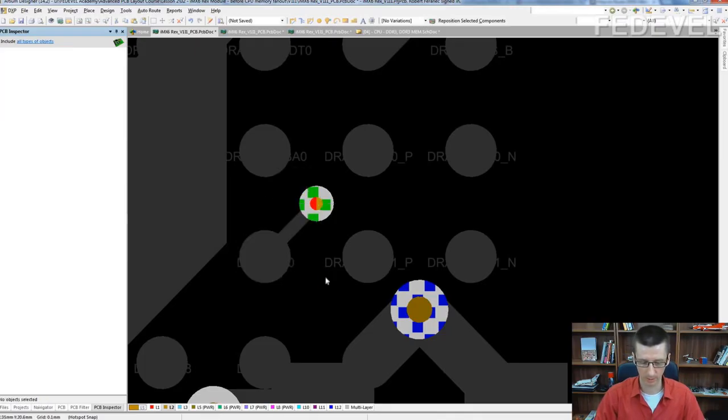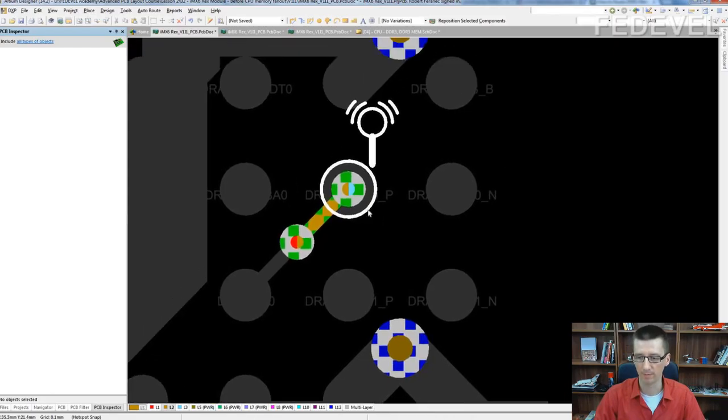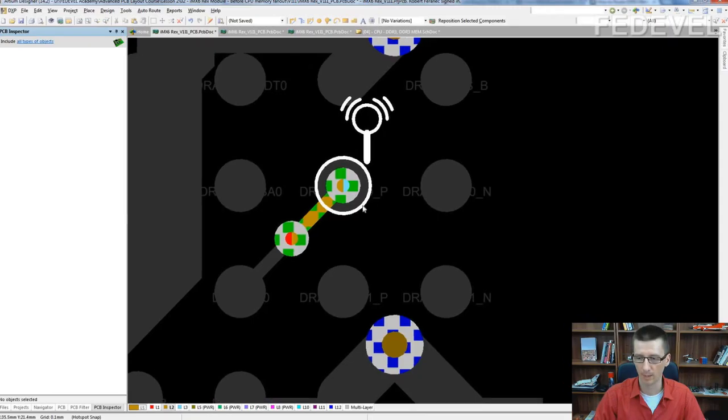It's only because I don't like placing micro via under a path with different net. If needed, you can do that if it helps with layout. I always also draw this L2 track just short and straight.